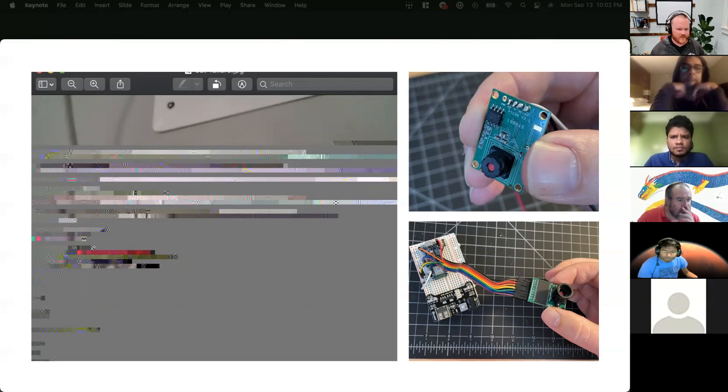I spent so much time with this little tiny camera trying to get it to work properly that it's sort of insane. I ended up rewriting the driver to work around some bugs that I think are in the hardware. I don't know how this is possible, but somehow the onboard firmware is shifting a byte every 300 requests or something. There's some overflow inside of the hardware that's making it mess up. So I was trying to write a driver that would work around this bug, and it was quite the rabbit hole. I did occasionally get full photos out of it, but it's pretty limited in how reliable it's going to be.